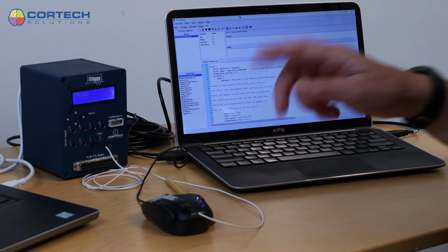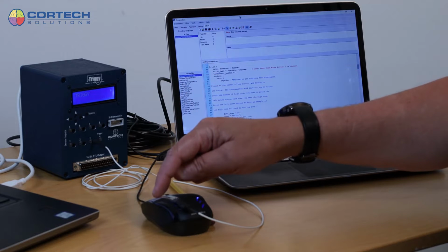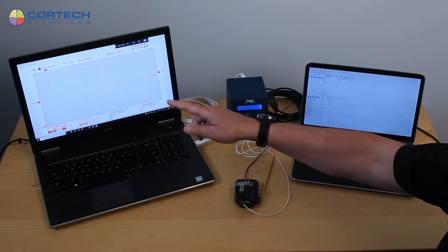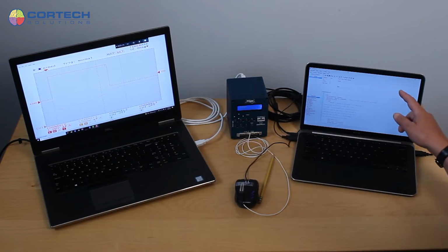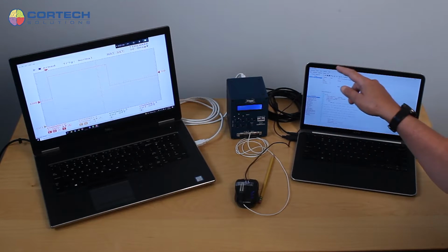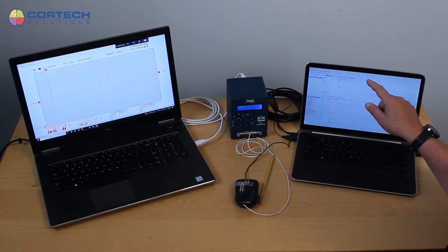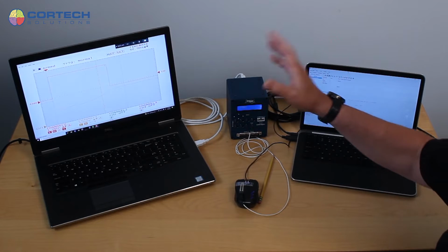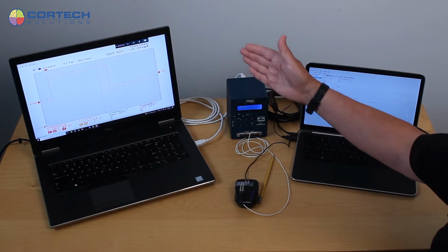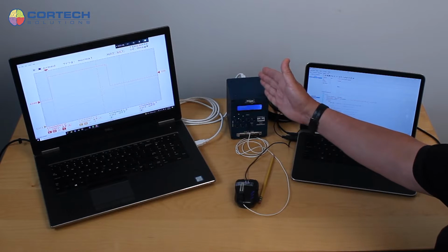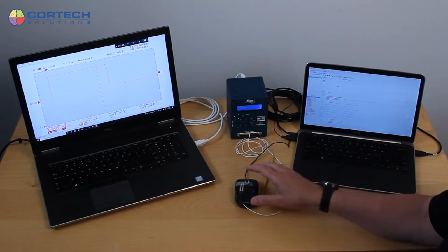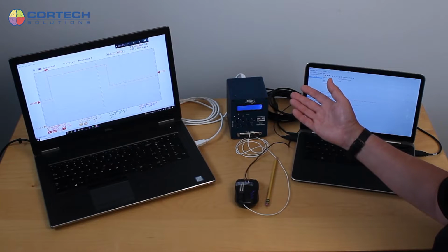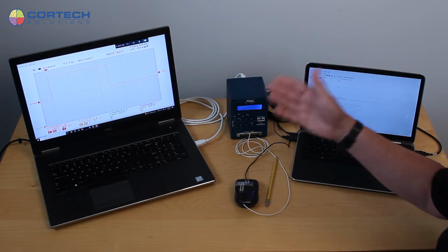So in the first instance, we'll check how the press of the button and the pressure signal relates to the TTL out from Triggy. But we'll also observe how, when you run an experiment that is measuring responses and outputting those responses, presumably to some other device that's recording both stimulus markers and response markers, you can use the pressure sensor to know whether or not the timing of those TTL outputs is accurate.